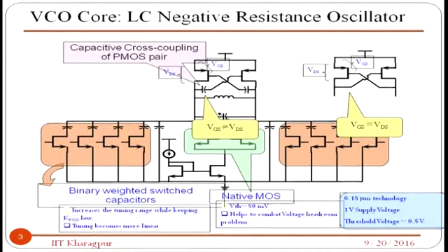But suppose the voltage swings up, then the difference between them is going down, and on the other hand, if the voltage goes up, then your VGS is going up. So, the condition VDS greater than VGS minus VTH is not satisfied in one condition of the signal swing, when it is going in the upward direction.